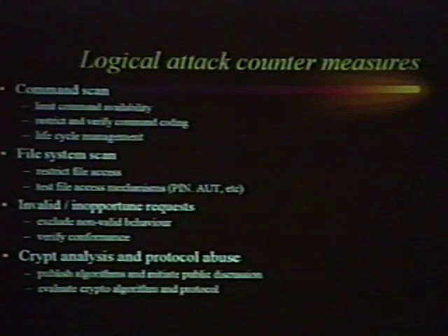So what can we do against all these logical attacks? If you look into the command scan, you need to limit the command availability. You need to restrict and verify command coding. And you need to enforce lifecycle management. Some commands may be available at an early stage, but they need not be available in the field. With respect to the file system scan, you have to take care that the file access is restricted, and of course the file access mechanism should be tested.